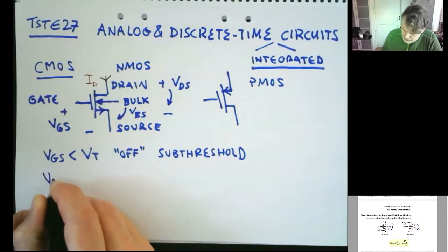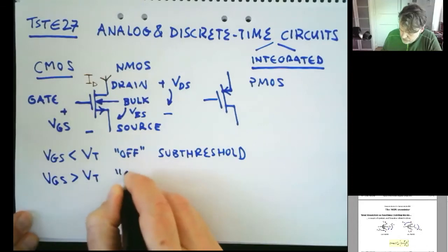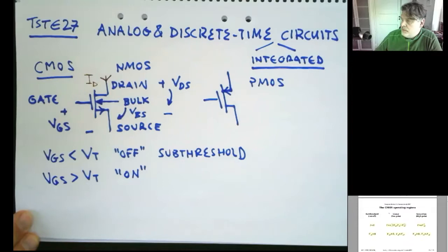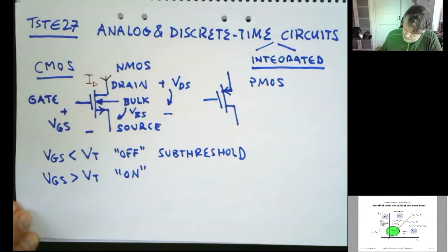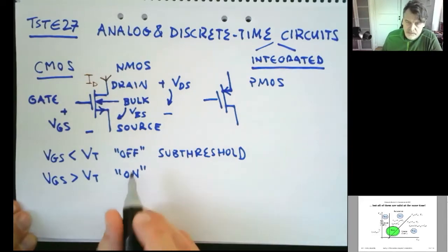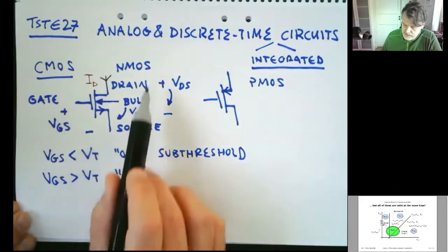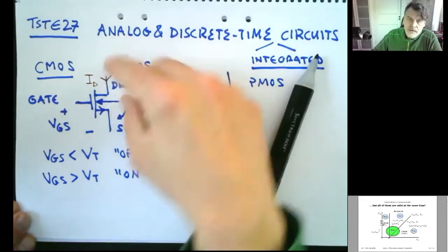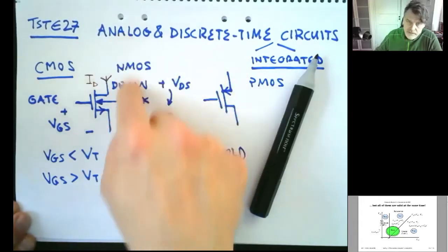Then we can turn on the transistor by increasing the VGS voltage. Then it's on. And then it has two sub-regions when it's on, dependent on how much voltage we have applied. It typically relates to the VGS voltage and the VDS voltage. So if we apply a large voltage from the drain to the source, we get a big field in this direction.